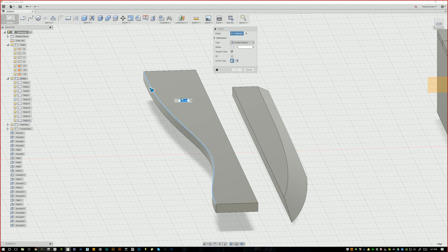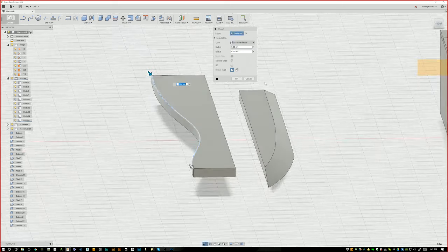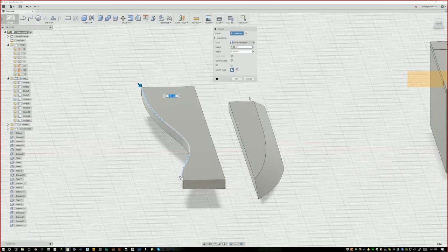Like right here in this little box? Oh yeah, don't even click it. I think the box kind of disappeared off your screen, but no worries. Here's this constant radius. Drop that and pick variable radius under the constant radius. Does that say variable now or does it say constant still?